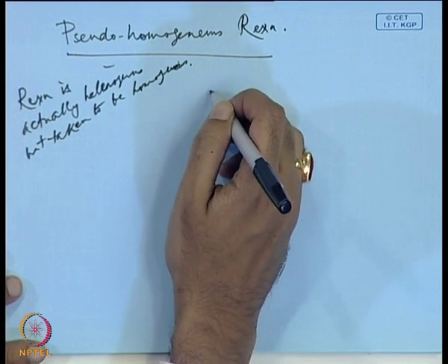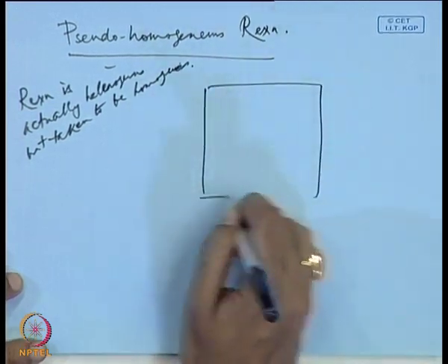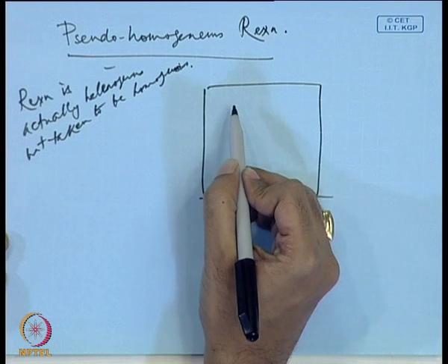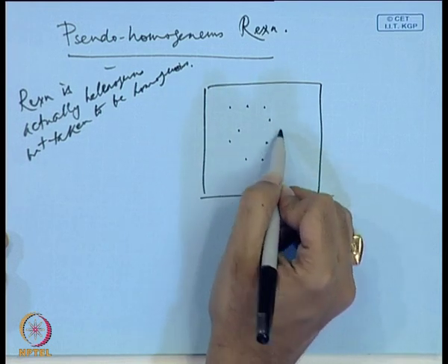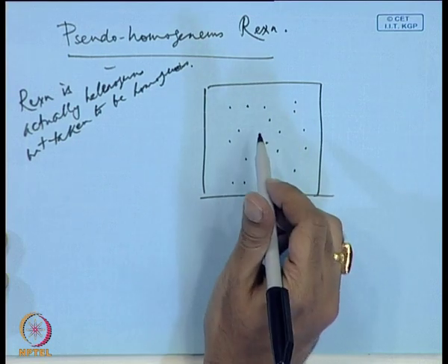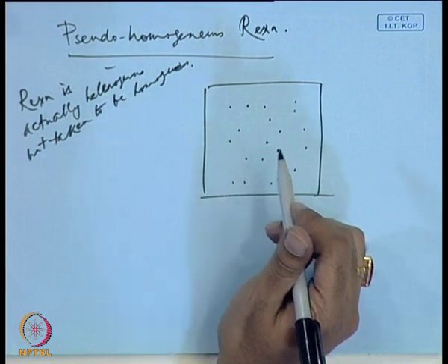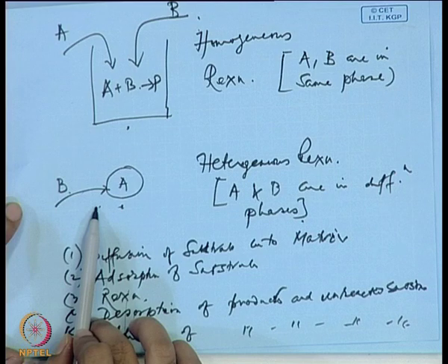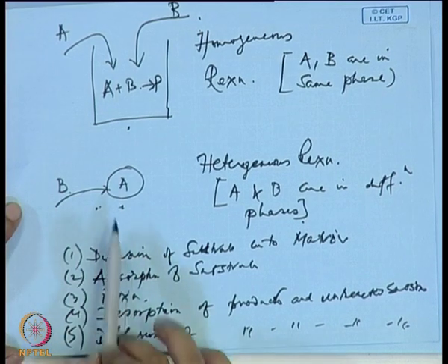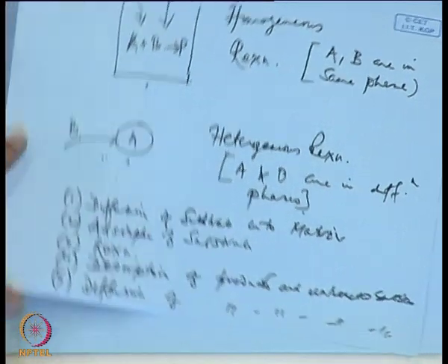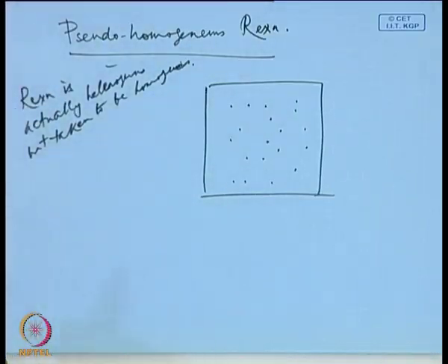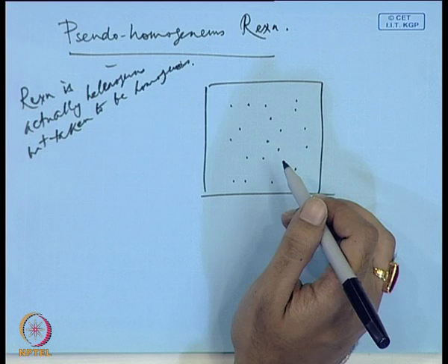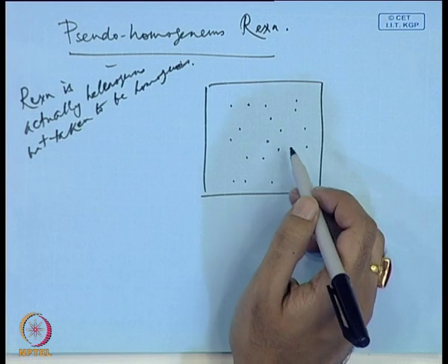Okay. Let us see, for example, you have these, say, in a catalyst bed or something. So, you have these different points of reaction. These are different catalyst pellets that are there. So, one way would be to look at it in a heterogeneous way: take each catalyst pellet and look at what is reaching this catalyst, diffusion, adsorption, reaction, desorption, diffusion, and so on. The other is, for example, you are lazy and you really do not want to quantify each catalyst pellet. There are thousands of catalyst pellets and you do not want to quantify each one, or even a single catalyst pellet.